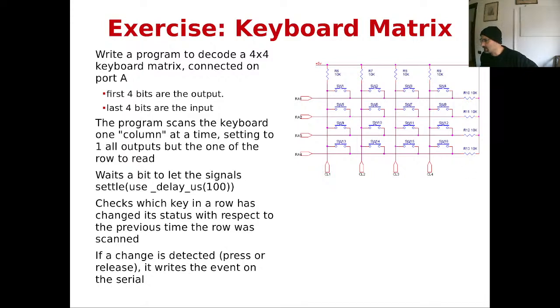Marco says, when the vertical and horizontal cross, there is a bridge, of course. If you see a cross here, these wires here are not connected. There's a connection only if you see a ball. This is the answer to Marco. Is there a connection here? No, there is no connection. The connection is only where you see a ball. Okay, so these 2 wires are on 2 different levels.